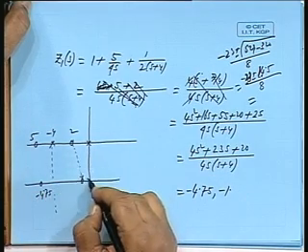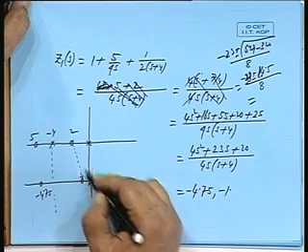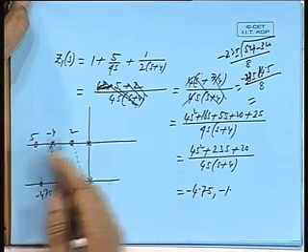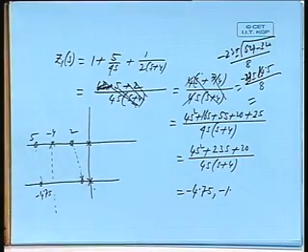We have weakened this pole at the origin, is it not? So, this zero is drifting to this side, this zero also drifts towards this side. That means all the zeros will be gravitating towards the pole which you are weakening, all right. Here both of them will be shifting towards the origin.